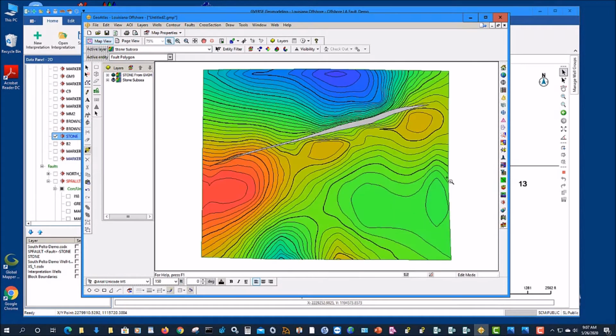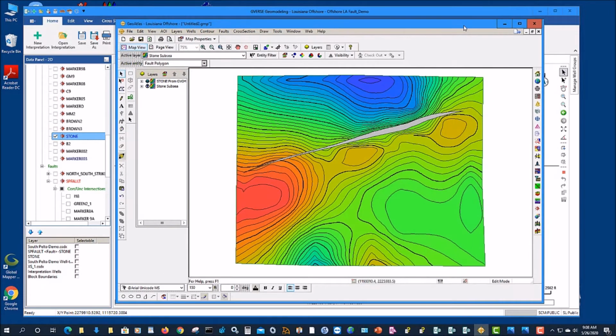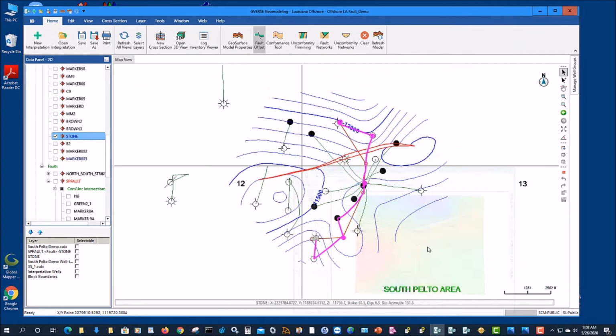And some years ago, when geomodeling was still a fairly new piece of software, we had a geologist out in California who used this particular workflow constantly. He had a kind of master IsoMap layer, if you will, and would use the modeling tool to add and edit faults, generate the polygons, push the layer up to IsoMap just like I did here, and then grab the new fault polygon in a new area, paste it onto the master IsoMap layer like I did here, and then regrid it so that the new fault polygon would be incorporated into the interpretation on that layer. Okay, so that's an example of an existing fault that was picked in the South Pelto area, and how you can use the fault polygon that was generated from a particular fault at a particular surface in IsoMap as well. So let me minimize IsoMap.